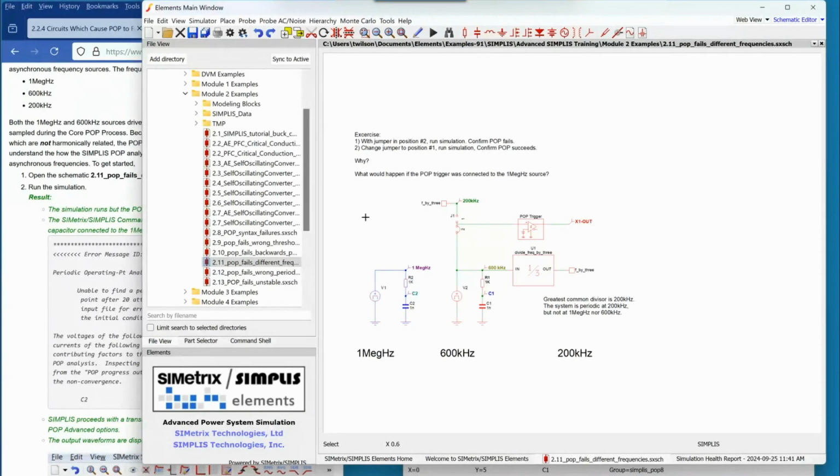Just an additional comment. If you have somewhere a capacitor that's not even switched, but it's initialized and it has a bleeding resistor on it, you run into the same problem, because that voltage changes gradually and the error is there at the beginning where it's largest, and it will fail. Right.